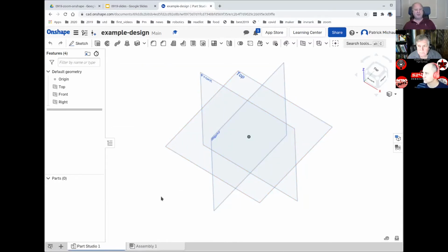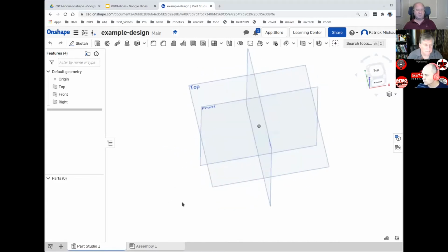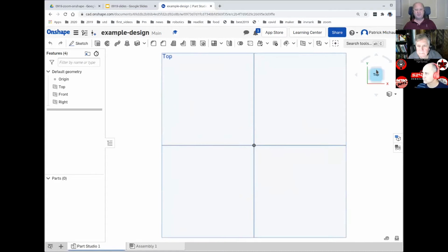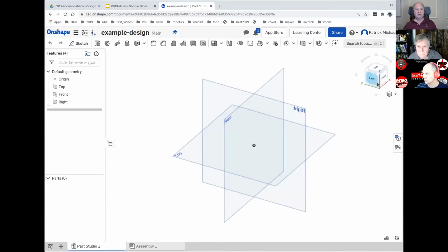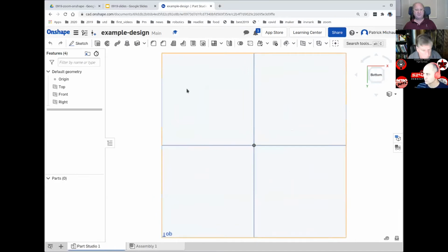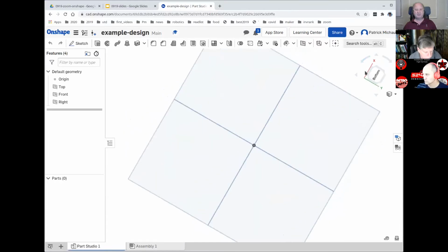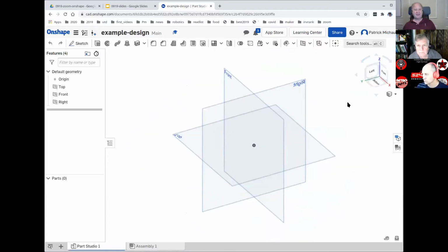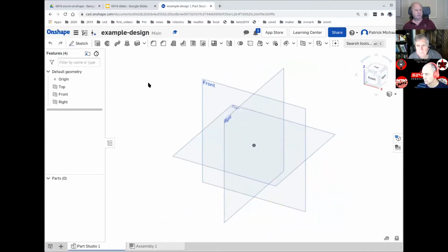And using the mouse, by holding down the right button, I can rotate the view that I'm looking at on my model. There's the view cube that's up in the upper right-hand side. And so if I click on top, it's going to let me look at the top view of the model. If I click on one of the corners, it gives me an isometric view from that corner. If I click on an edge, then I can look at different edges and do different types of motion that are there to be able to look at the model in different ways.